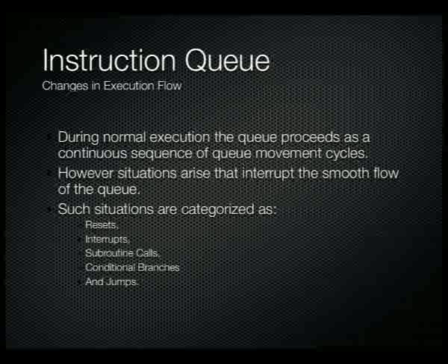There are other situations that also upset our instruction queue, and these are of course when we have a reset. So when you turn the power on and off, then of course it's got to jump back into memory somewhere else, so it's got to jump to wherever the reset vector points to.